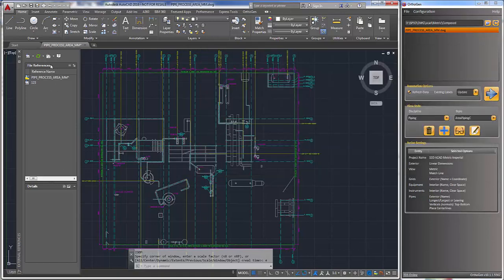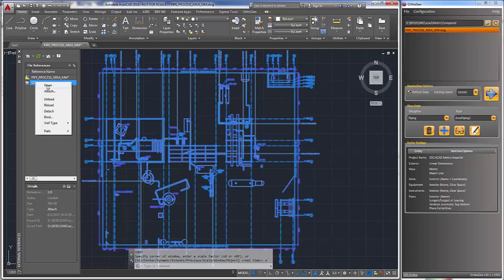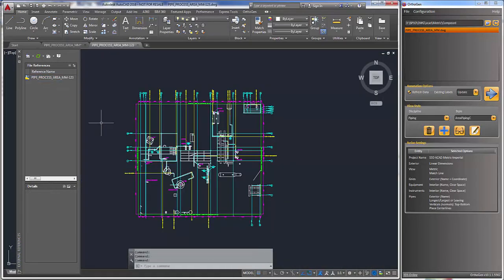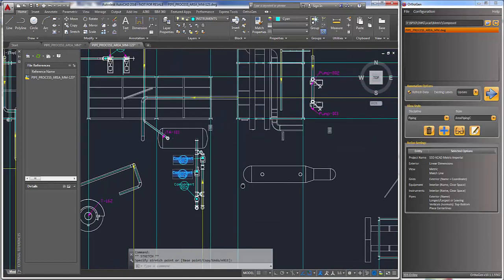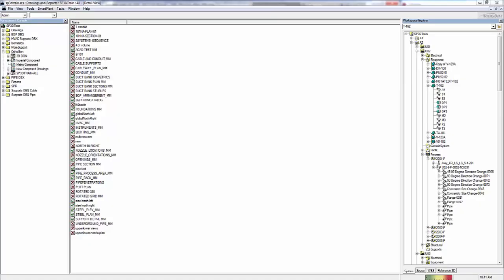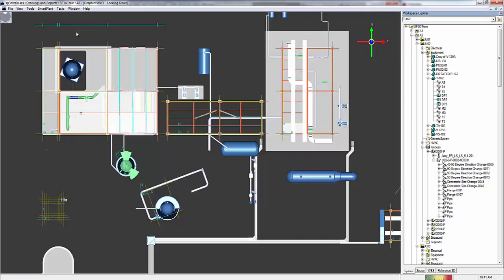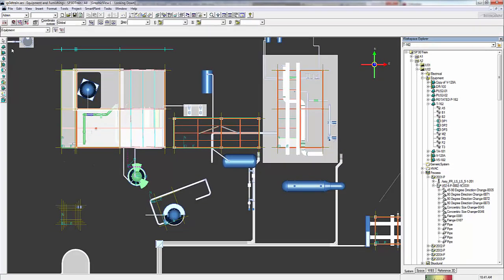Once the annotations are complete, you have the capability to modify the drawing using the CAD system. In this example, we select the XREF containing the graphics information. Opening the XREF, we can now rearrange any labels that were not placed as you wanted. Orthogen tracks the manually moved labels and will leave them where you placed them. After embellishing the view, the drawing can be updated at any time to reflect the latest model conditions.